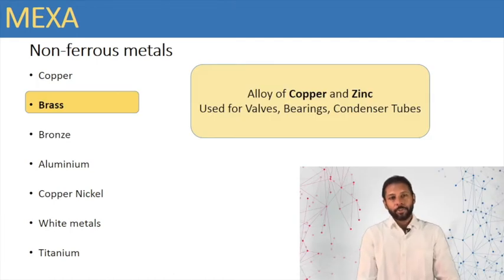Brass is an alloy of copper and zinc, usually with a predominance of copper. When brasses are in contact with corrosive conditions, either atmospheric or seawater, they may dezincify, leaving behind a porous, spongy mass of copper.